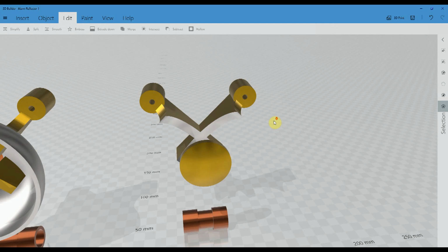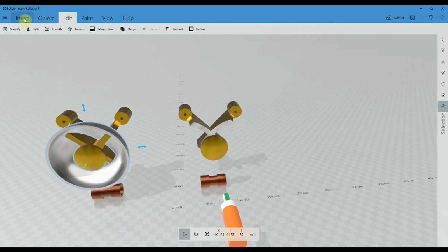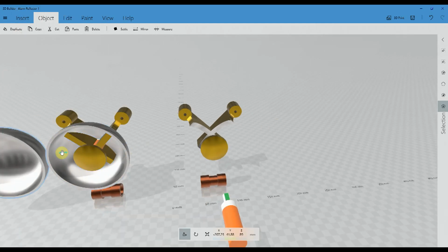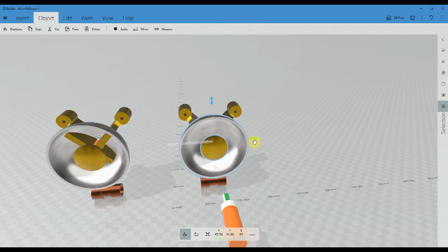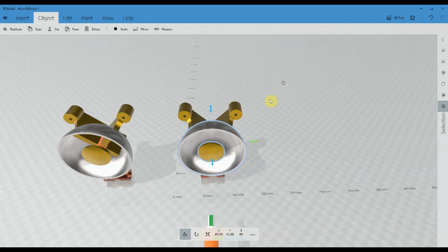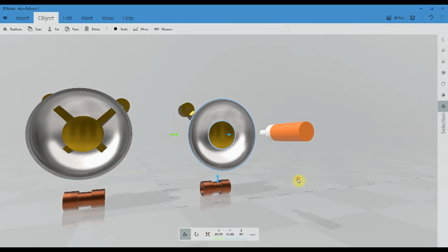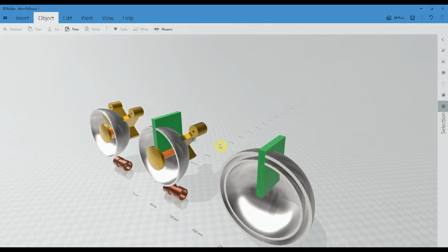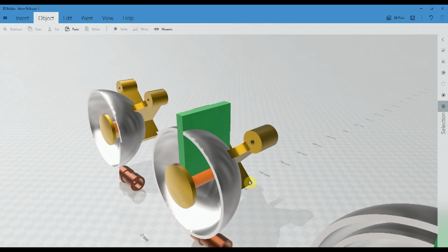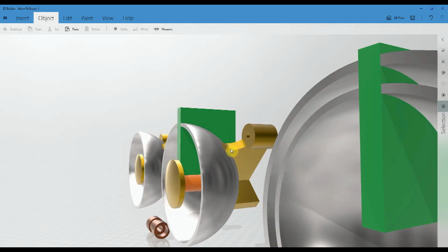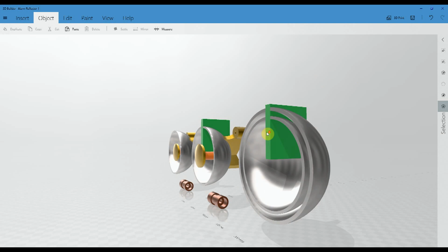One thing which is really useful is that because all the objects have a center, I can get it lined up really accurately, because I seem to remember it's 67.76 millimeters it ended up being as the center. So all the different components, if I selected them, I could say, okay, I want X to the right to be 67.76. Now the next exciting job is to make some sort of finger-like objects that will grip and hold and support the reflector.